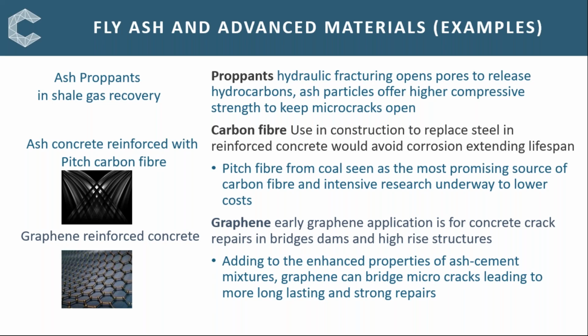The other two examples are concerned with the application of carbon fiber and graphene. Carbon materials are becoming more significant, and when combined with fly ash cement, offer a new higher level of bonding. And there's considerable interest in this, as it reflects on concrete durability. Carbon fiber could replace steel in reinforced concrete, and that offers a material that is then corrosion resistant, with implications for the lifespan of essential infrastructure.